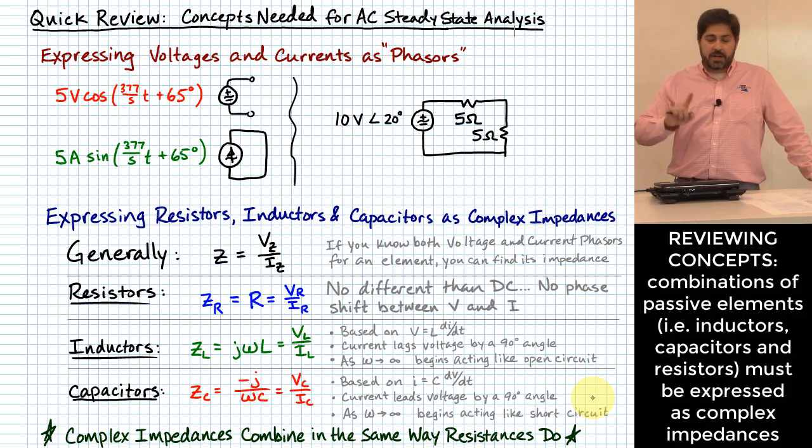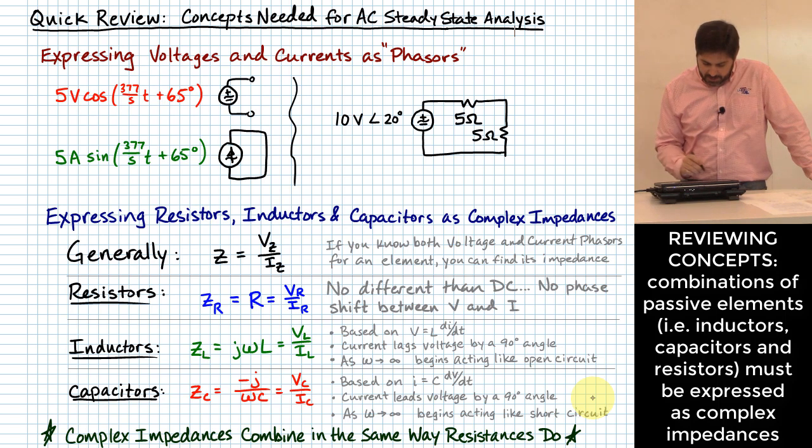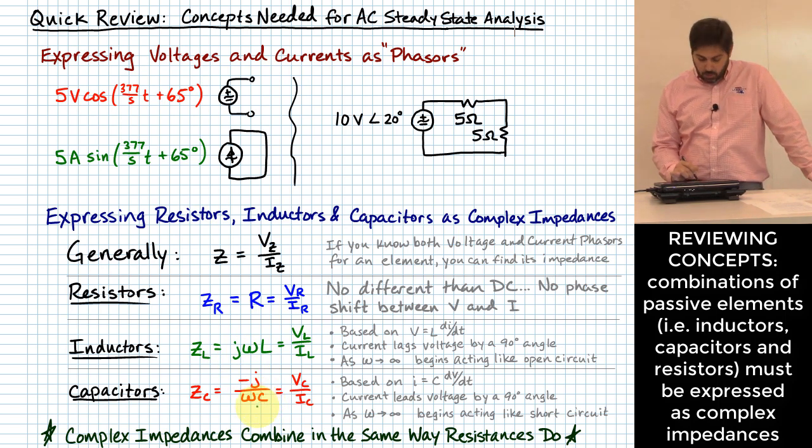Then you saw a lecture where we could convert circuit components, particularly inductors and capacitors, from inductance or capacitance values into what are called complex impedances. That's what I have near the bottom of this page: formulas we can use to turn a capacitance value, in this bottom one, into a complex impedance, or turn an inductance value into a complex impedance. That's one of the other pieces we have seen so far.